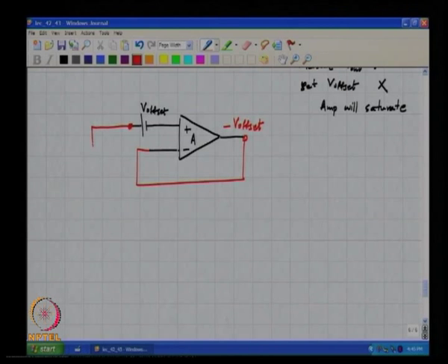Okay. So, in other words, let us call this phase phi AZ, the strange choice of clock name. AZ stands for auto 0, right, and is the trade name given to any technique which removes offset. Offset cancellation is also called auto zeroing.